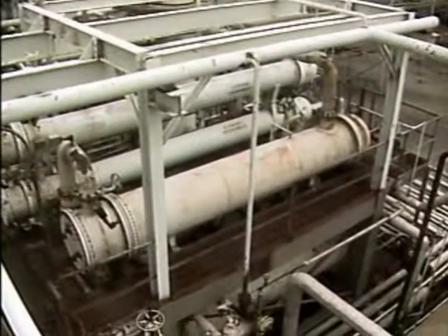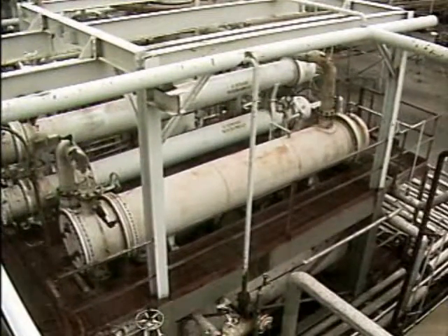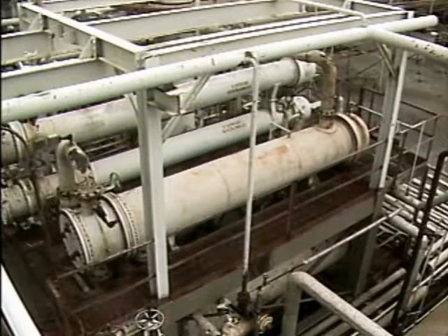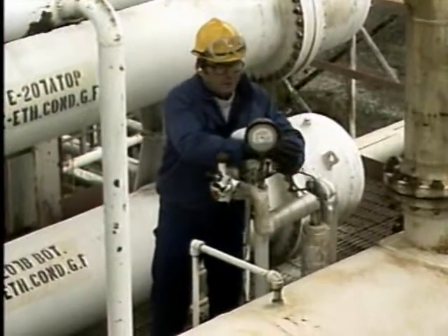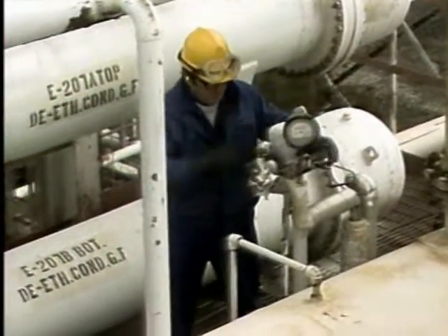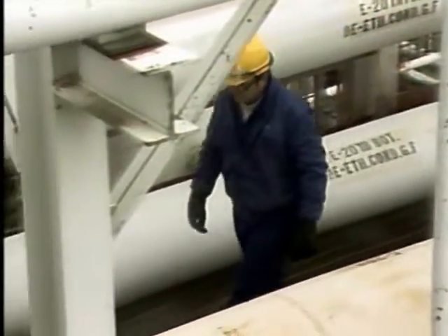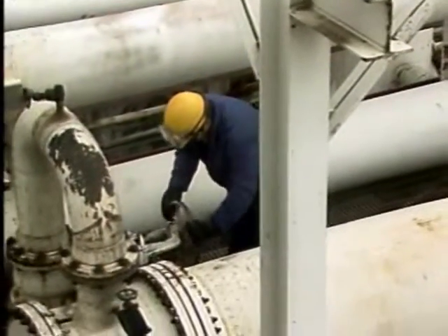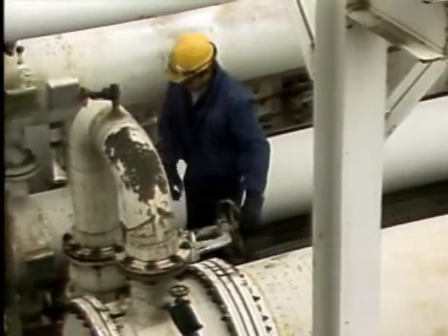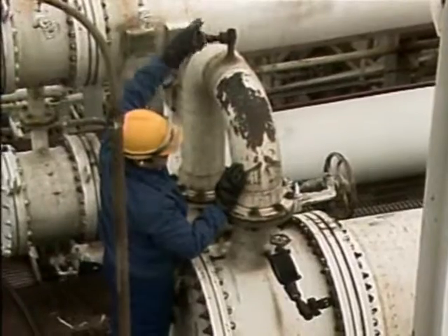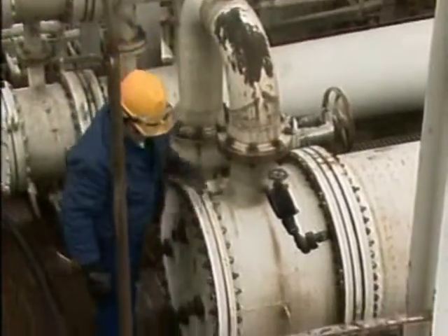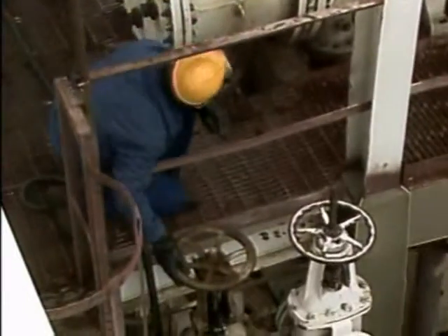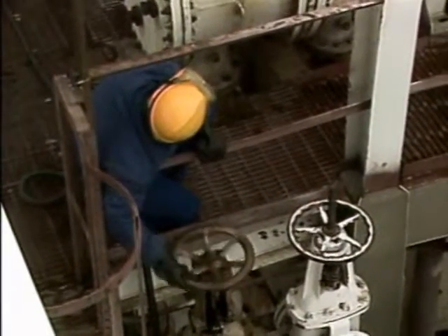It operates at a pressure well above atmospheric, and the cooling in the condenser is accomplished by water that passes through the tubes. Before starting up this condenser, the operator verifies that the valves on the condenser and its associated equipment are properly lined up according to his startup procedure. With the valve checks completed, the operator opens the vent valve on the tube side of the condenser. Then he partially opens the cooling water inlet valve.